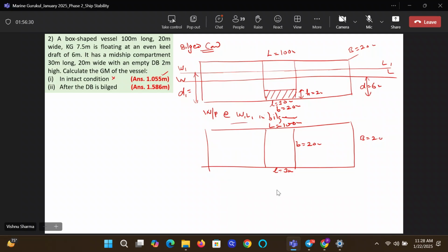Now, talk to yourself like this. I'm prompting you. Write down like this: sinkage, and you will write in the notational form. Lost buoyancy: look at the upper diagram and put the lost buoyancy in the notational form. And in the denominator, the intact water plane from the lower diagram. And find out the sinkage. How much sinkage have you got? Tell me, guys.